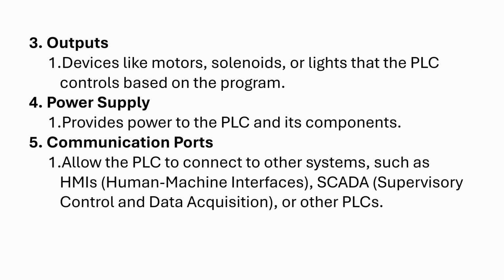And then you've got communication ports, which allow that PLC to connect to other systems. You might have HMIs. HMI just stands for Human Machine Interface. It'd be your display, like a touch screen. Also SCADA, which stands for Supervisory Control and Data Acquisition. You've got a lot of SCADA systems out there. I'm familiar with GE iFix. There's Wonderware, also Ignition from Inductive Automation. That's a really good SCADA type system, or even other PLCs. You can have large systems with multiple PLCs that need to communicate together.